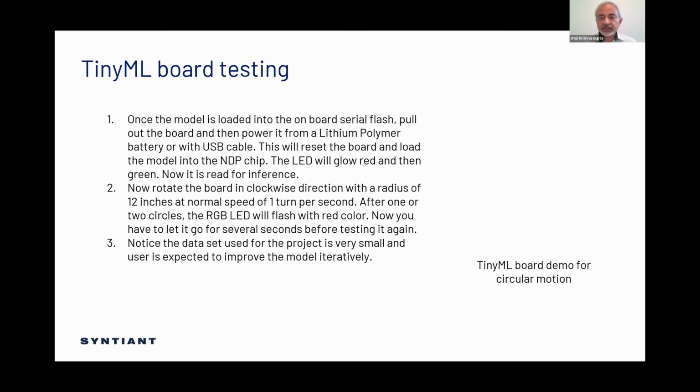One thing to note is that by default, the posterior filters are such that it would not trigger the same classifier over and over when you continue to do that kind of motion. That is done for good reason, because every time the NDP chip asserts the interrupt, the host has to wake up, and you don't want to be waking up the host over and over.